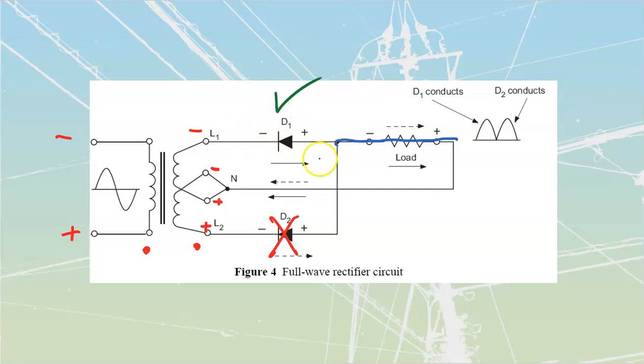And so now, I'm going to be able to pass current out of my transformer. Transformer is an electrical source. Pass out of that transformer through that diode. That current isn't going to go down here because that's blocking. There's no complete path, so it's going to just pass through here. Going to come back along that line over there, and then it is going to travel up through there. We've got a complete circuit over here, complete path for current. We see that once again we have driven current through the load in the same direction. That is what full wave rectification is going to be, that we're always going to be looking at driving current through the load in the same direction.